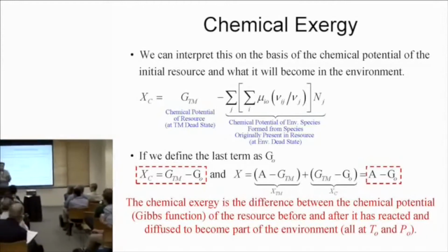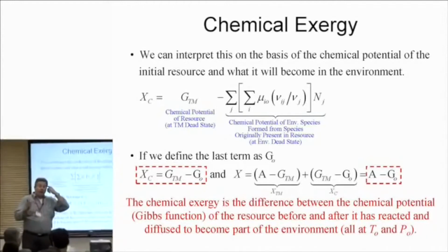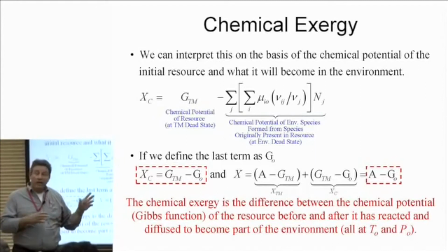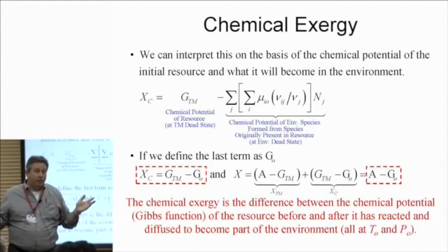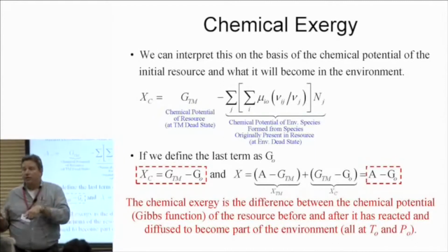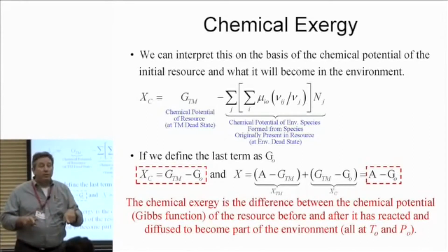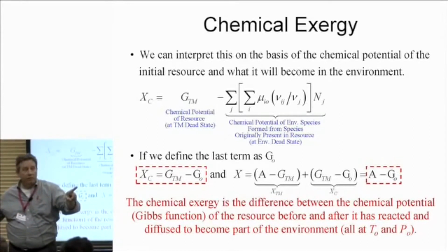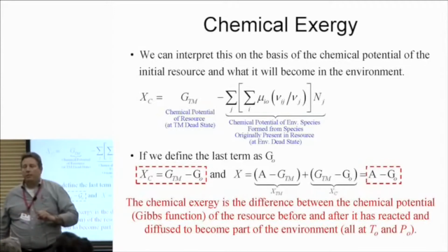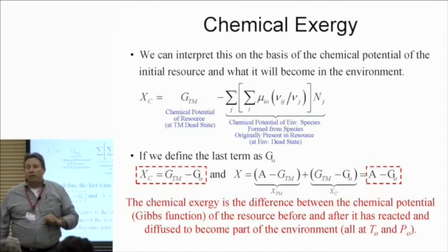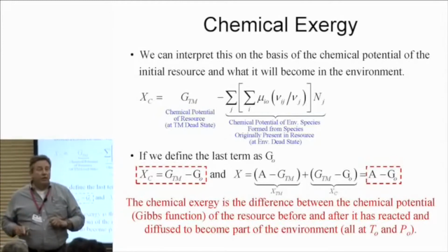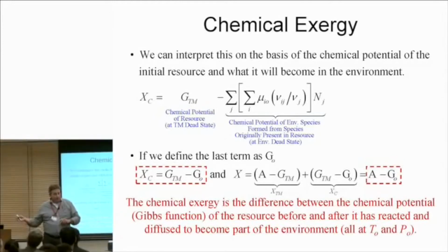Yes, with one additional caveat. If I had a mixture that was stoichiometric or lean, say a combustion mixture, I could use delta G of reaction, take the final composition and do a diffusive exergy calculation into the environment for the chemical potentials. But let me tell you what you can't do, because people try to do this. Go to the rich side. On the rich side, you can't use that original delta G. You've got to make all the intermediate compositions from it.